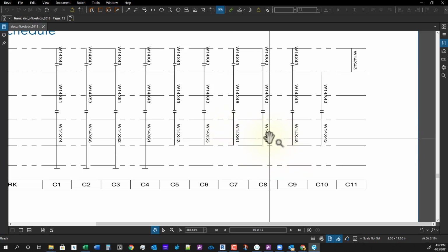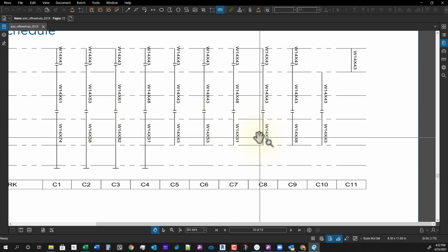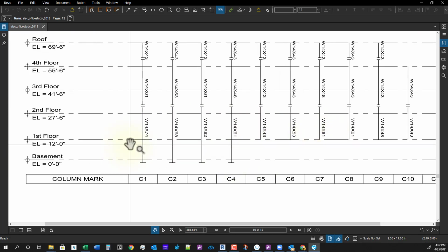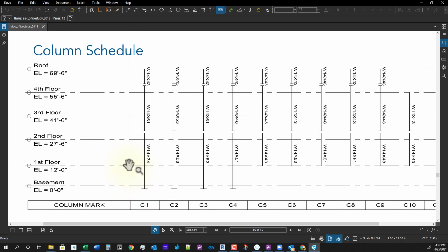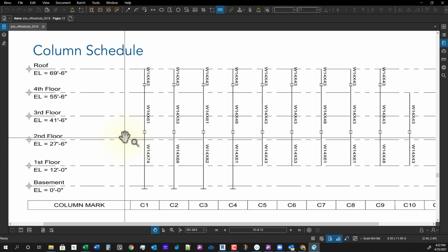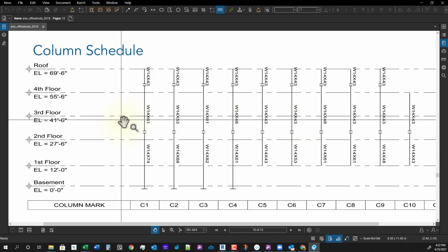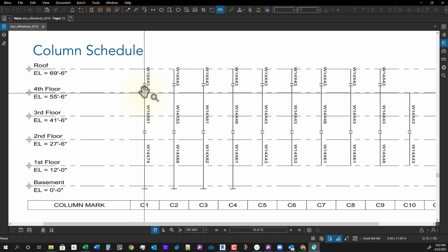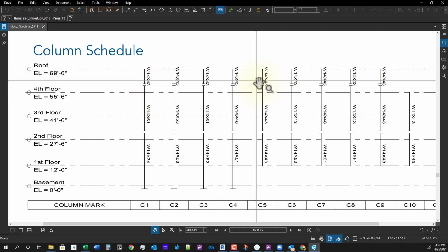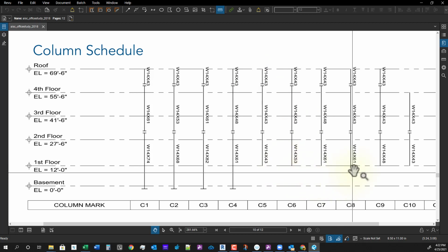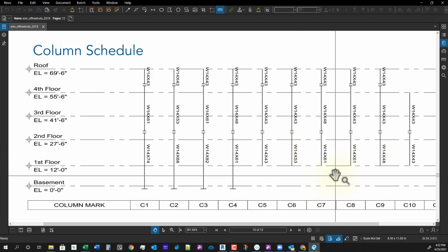Let's start by using that for most of our floors. And you can see here the column shows where the floor starts, and then it goes up to the second floor. This next row column starts at the second floor and goes up past the fourth floor, and then they have different columns at the roof. So for this exercise, let's just use the 14 by 61 column throughout.